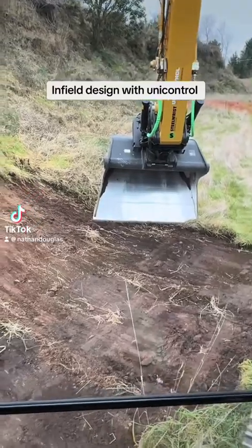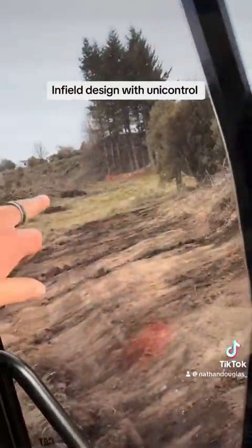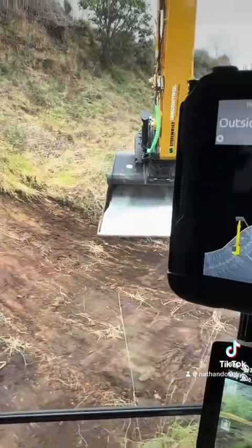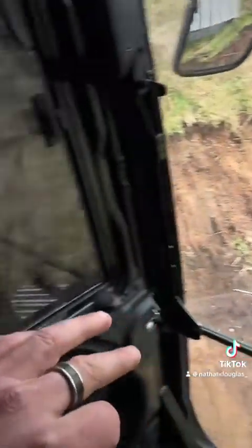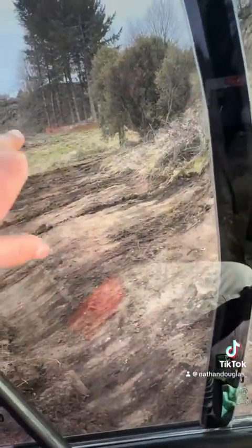I'm going to make a design that runs from here, a swale around through to where those trees are. So I'll just create a slope through here. We're just going to pick up a couple of points, and I'll add a point here, and then I'll go through and add a few points all the way along and change their RL focus, and it'll create a line, a poly alignment to follow.